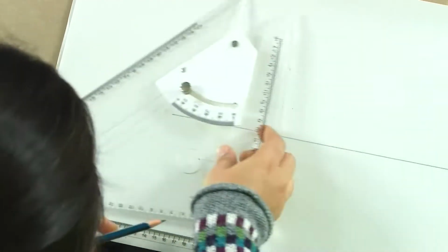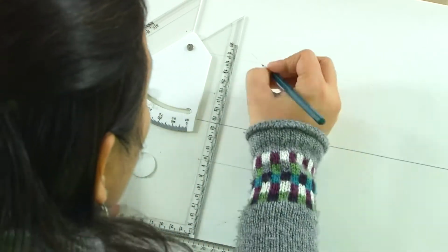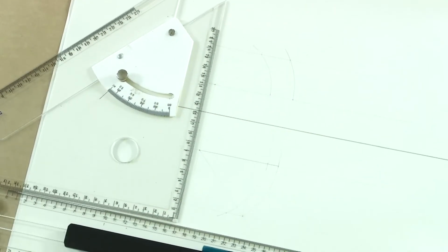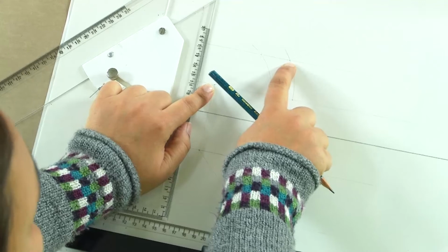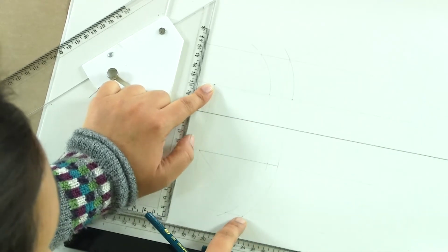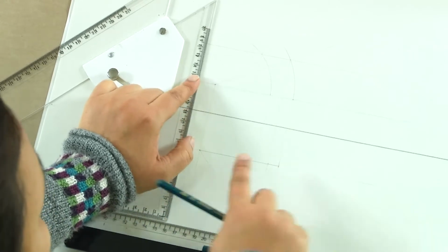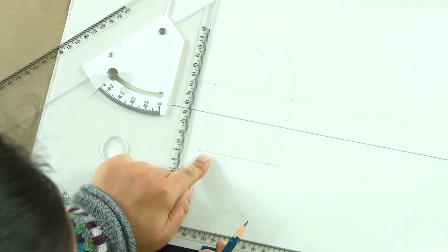So, I am doing simultaneous drawing, but if you see, this is the point and this is the point here, which ideally should match in a straight line, because now here what we have done, we have taken the projection of this line which was inclined at HP to a locus, to a line, a path which is obtained by inclining that same line at 45 degree to VP.